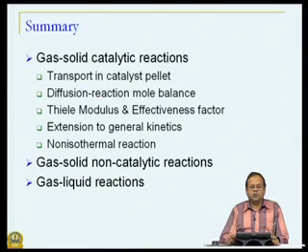The major difference between the catalytic and non catalytic reactions is that the solid we are looking at in a non catalytic reaction is not a static material, but it is dynamic, that is, its size for example changes with time, and therefore gas solid non catalytic reactions are time dependent processes, whereas in catalytic reactions we could easily assume quasi steady state as far as the diffusion process is concerned and look at the steady state analysis.